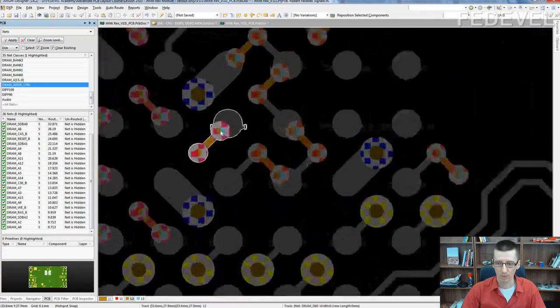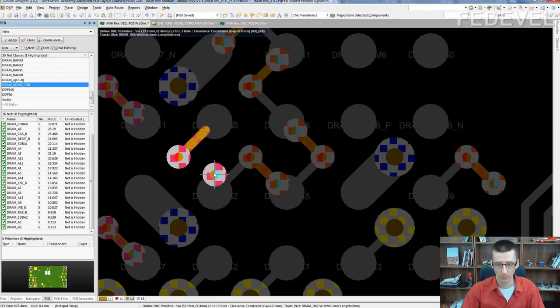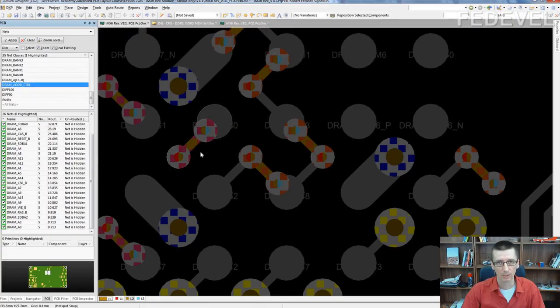About these short tracks on layer 2. When we were speaking about these microvias before, I always placed in the examples I showed you this microvia exactly under a pad. It is not required to place this microvia under a pad. Important is to keep this track short, so the ground on layer 2 is as good as possible.